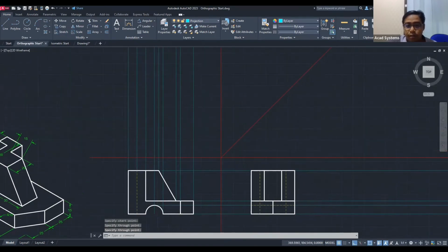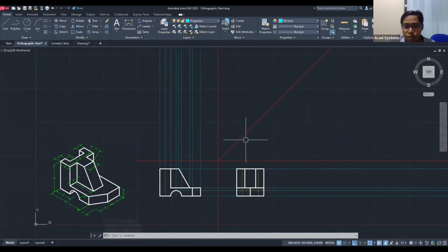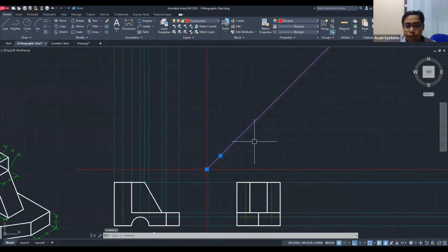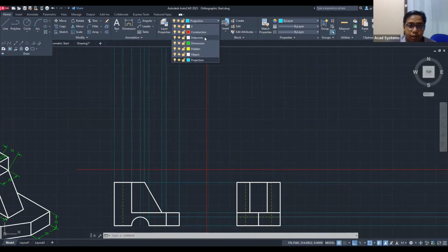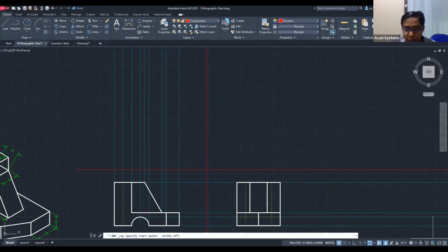And another one is the side view that I want to project to the top view. Again, make sure this line over here is 45 degrees, so it will have the same angle from the top and also at the bottom over here. So for that, when you create the ray line, make sure to have the angle of 45. So I'm going to create that and enter 45. So it will be 45 degrees.